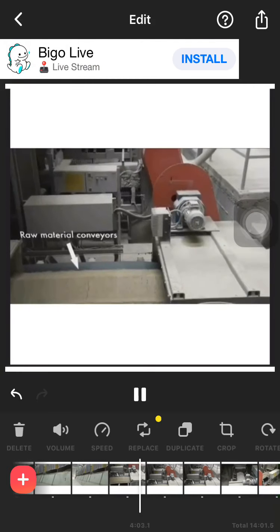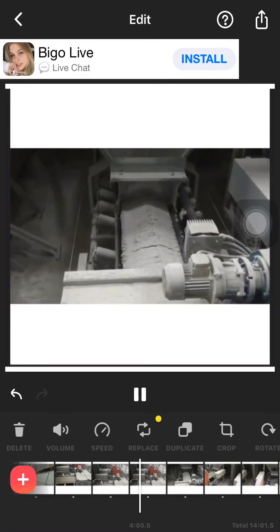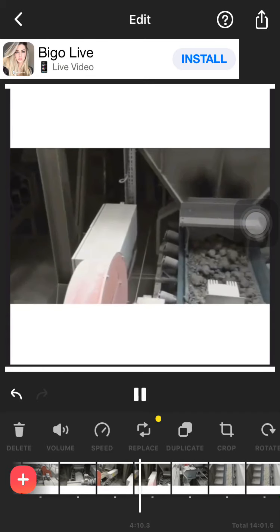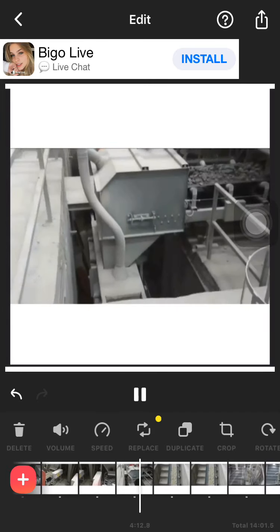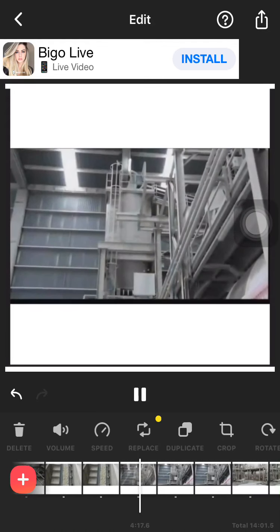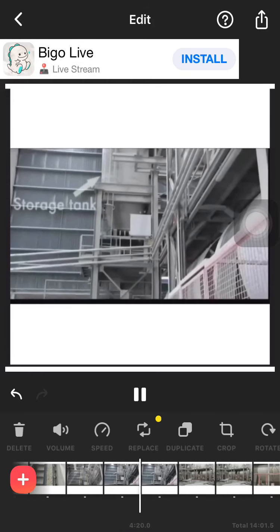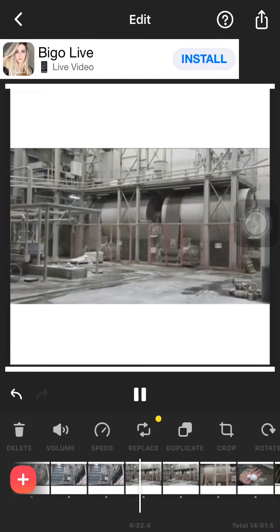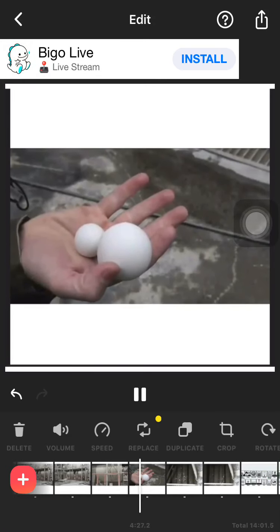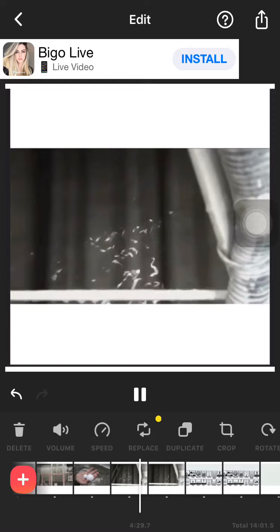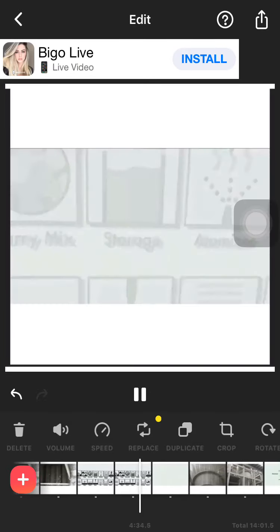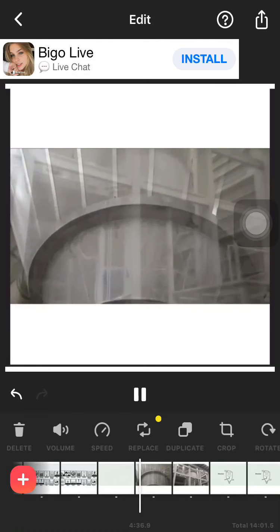The raw materials are mixed in specific proportions by weight. The specified mixture is achieved by varying the speed of the conveyors that feed a master conveyor. The conveyor dumps the mixture of raw materials into a storage tank. The mixture is then fed into a series of mixing tanks with water and ceramic pellets to form a liquid material called slurry. The slurry is then transferred to large underground storage tanks, then fed into an atomizer.